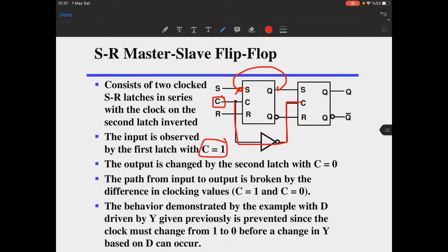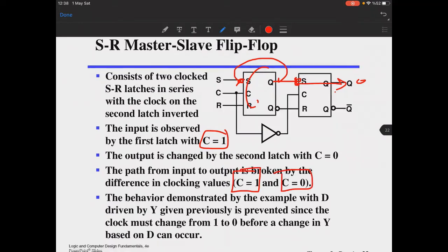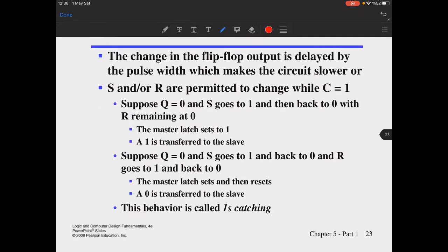Now, when your C0 signal comes here, it's waiting here, and they're not allowing it to pass here unless you provide here 0 now. Then it is allowed to pass here, and that's it. So master slave. So it's a 2-stage here. It means that you need your signal to go to 1 and 0 to take the input value, have an effect on the output value.